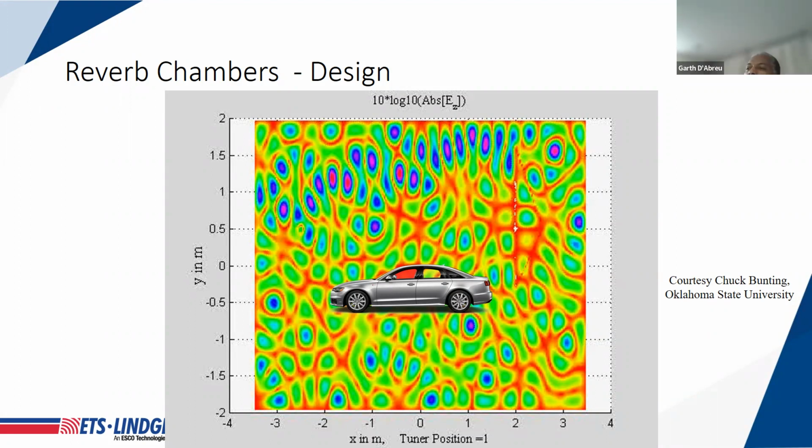Okay, so yes, as I was saying, one of the advantages is the extension at the bottom end of the frequency range. So for instance, if you're driving this cavity with an E-field structure or a low frequency antenna, where you don't have enough modes for stirring, the document gives good guidance on what the implications are of the increased uncertainty with making measurements at those low frequencies. So I think it'll be very useful.